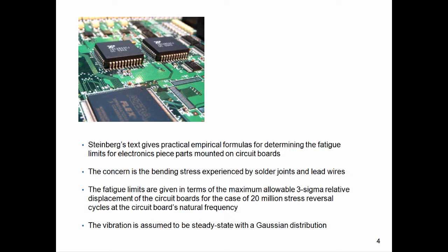So you get the idea that these avionics boxes are going to have to withstand non-stationary, non-Gaussian vibration. We may wish to model that in order to get a more realistic estimate of whether or not the circuit board and its piece parts are going to survive the expected environments.